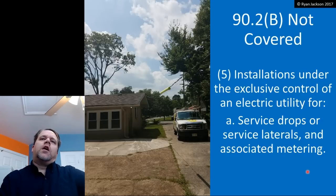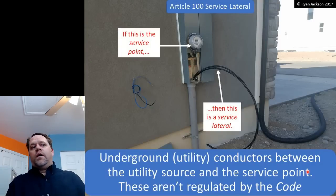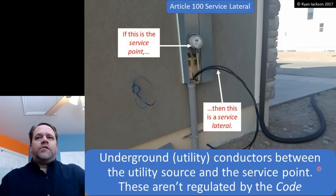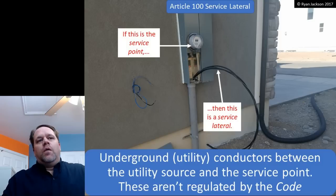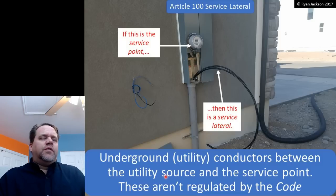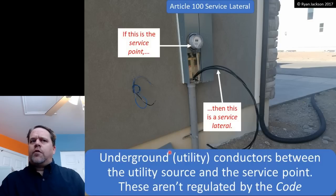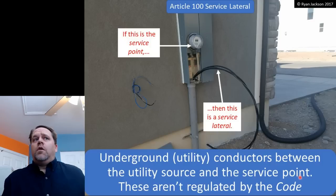Now, what's a service drop or a service lateral? And we have to go to Article 100. A service lateral is defined in Article 100 as the underground utility conductors between the utility source, so the transformer, right, and the service point. And they're not regulated by the code. Okay, well, I know what the utility source is. That's easy enough. So the transformer, right, the power source. But what's the service point? Again, a service lateral is underground, starts at the transformer, ends at the service point. So we need to know what the service point is so that we know what a service lateral is.